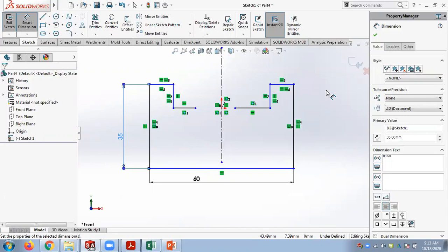But if you talk about a vehicle engine, and you have unstable sketches everywhere, if you change something, the entire engine model will collapse. So your drawings will fail. There will be a lot of issues coming when it comes to complex designs. That's why I'm stressing this underdefined, fully defined theory.